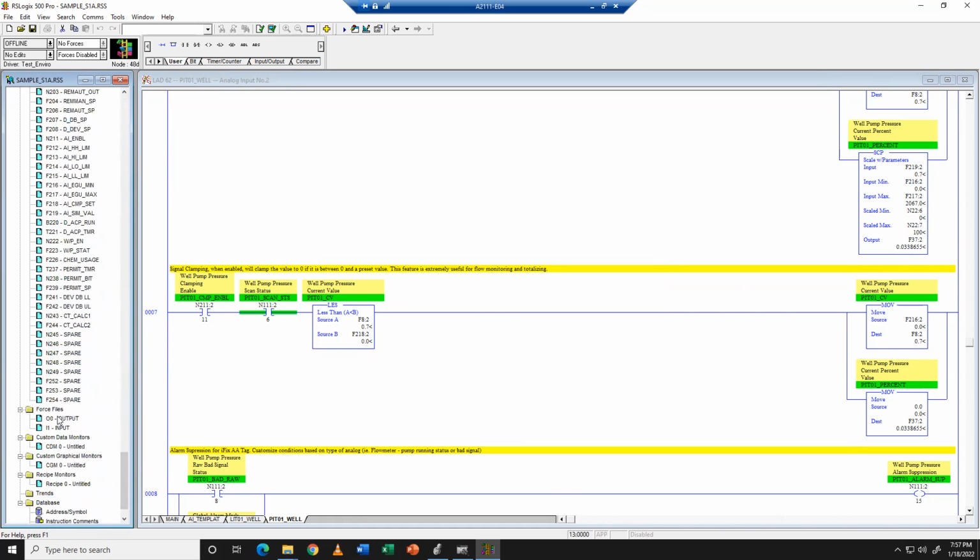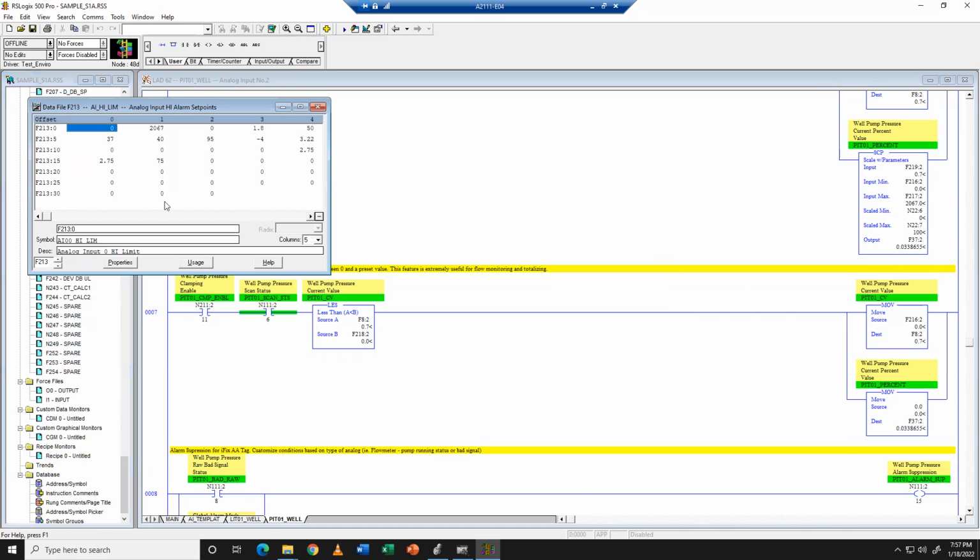There's lots in there as long as you organize it in a logical way and don't waste it. If you don't need 255 of something and you only need 30, only make 30. If you ever have to size microprocessor data tables or processor data tables, it's an iterative process where you need to know what you need to program before you program it. Then once you program it, you need to go back, reevaluate what you have, and shuffle things around.